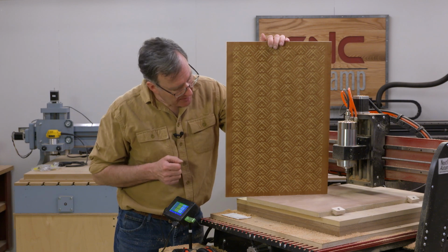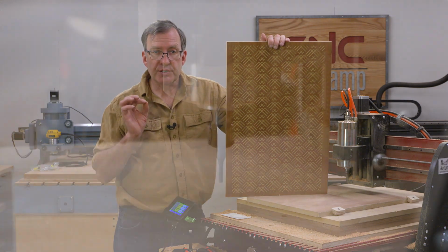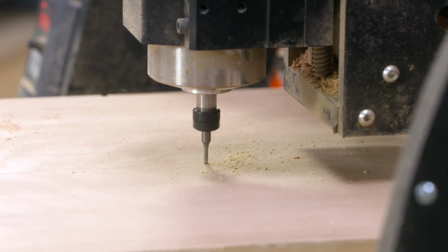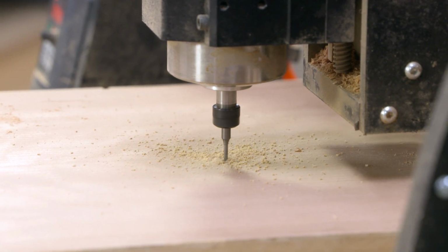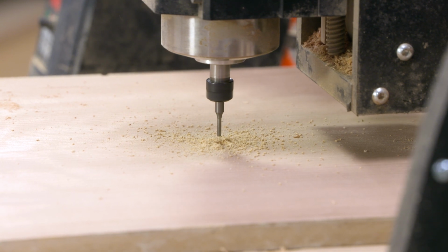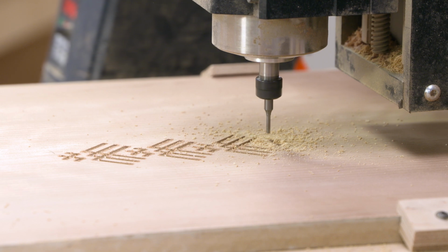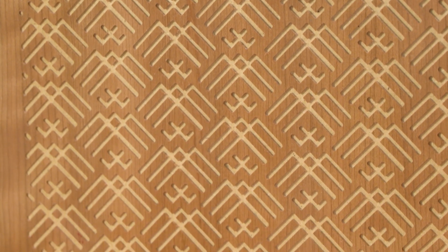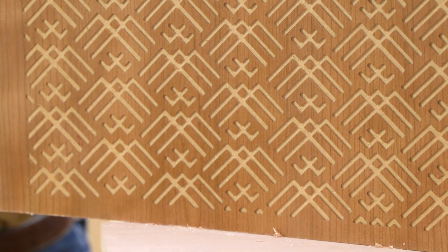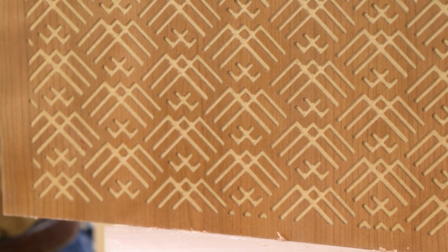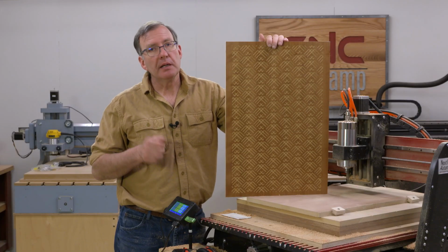The bit that I'm using to cut this is a 1/8 inch straight bit. Now that does produce slightly rounded corners in the pattern. If I want to tighten that up a little bit, what I can do is use the 1/8 inch bit to remove the bulk of the material and then go back with a 1/16 inch bit that traces the outer profile. And that'll really give you a good, sharp, crisp looking detail. Now I think this looks pretty good with the lacquer on that cherry, but if you'd like to add a little color, it's an easy thing to do.